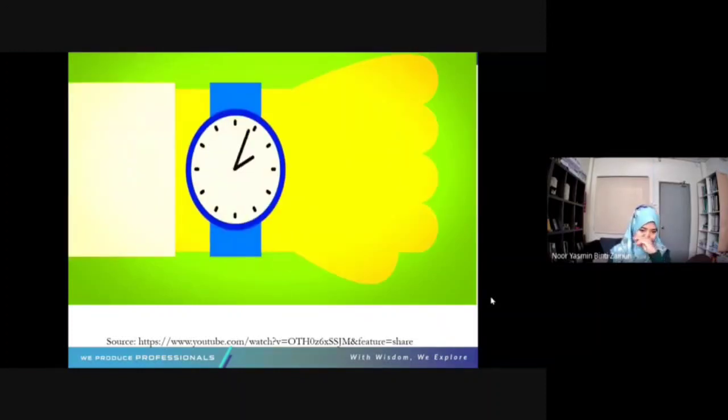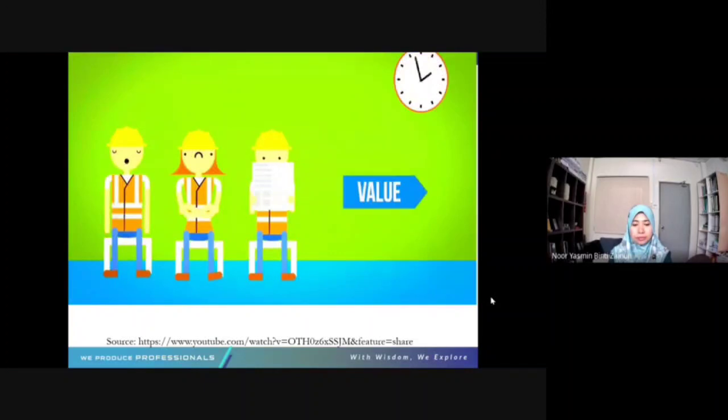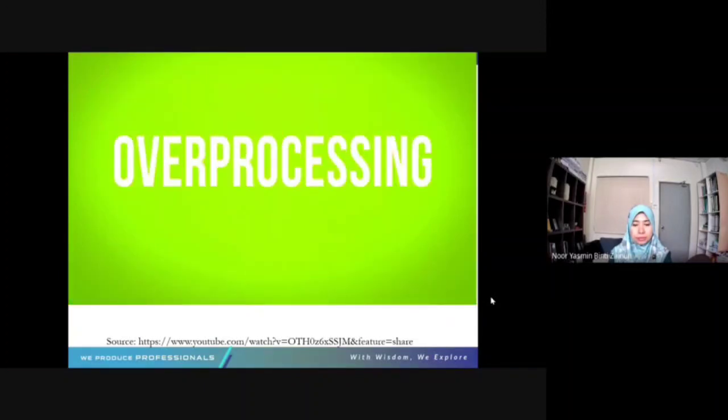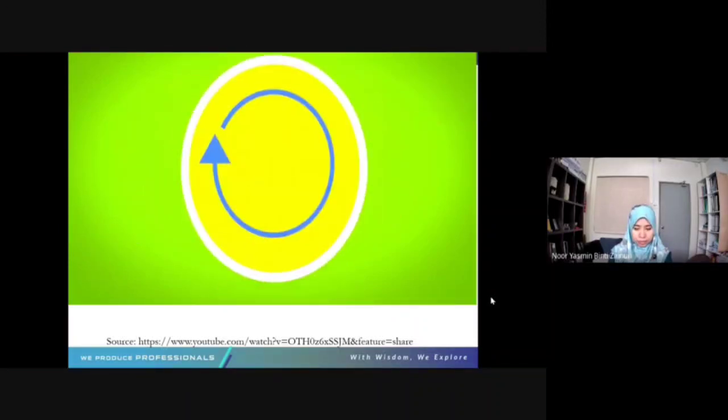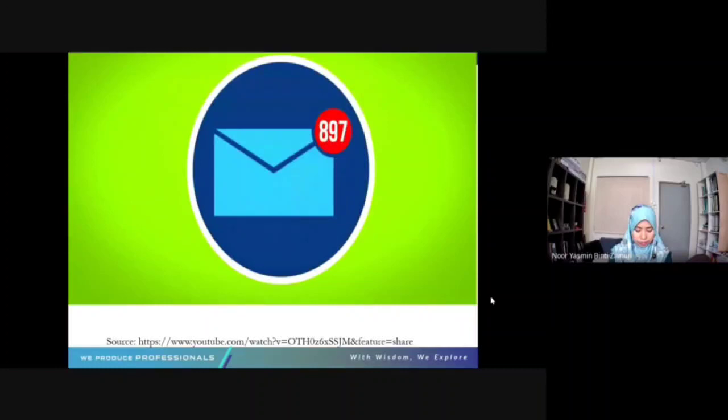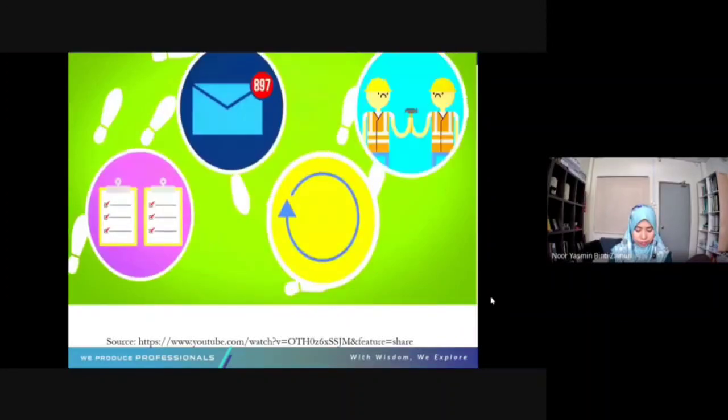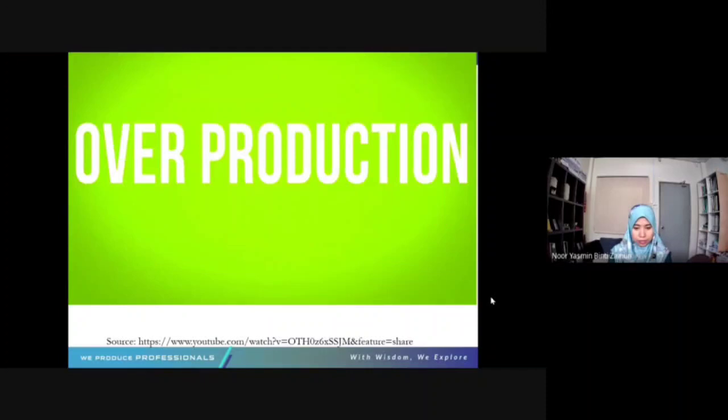Waiting: waiting refers to the periods of inactivity that occur because a preceding activity didn't deliver on time or finish completely. Waiting waste increases cycle time during which no value-added activity is performed. Overprocessing: unnecessary steps in operations, such as reprocessing, double handling, added communication, and double checking, which add no value. Overprocessing is often inserted into a process as a result of dealing with defects, overproduction, or excess inventory.